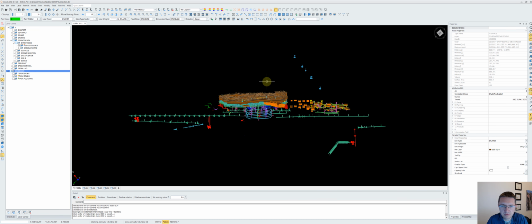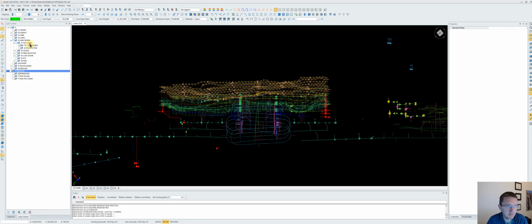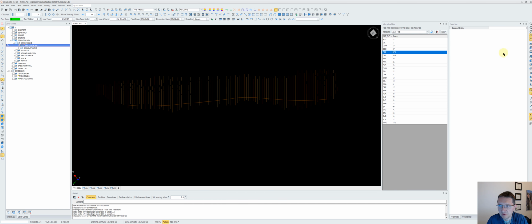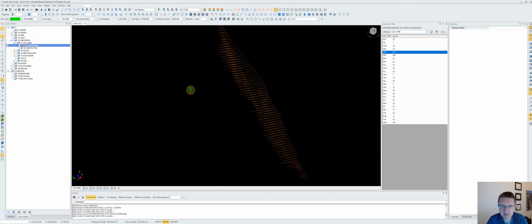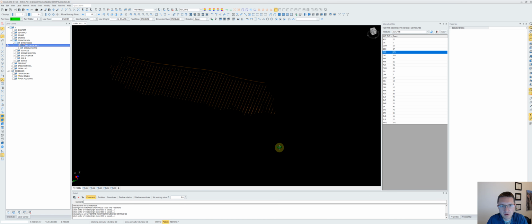So let's create the master ring set. Right here I have my center lines from the final design there. I'm just going to go and create an interactive filter, and I have the activity type up here. I'm going to say draw point rings. So these are my draw point rings right here. I'm just going to take these and extend them, let's say 50 meters into the hanging wall, 50 meters into the foot wall.